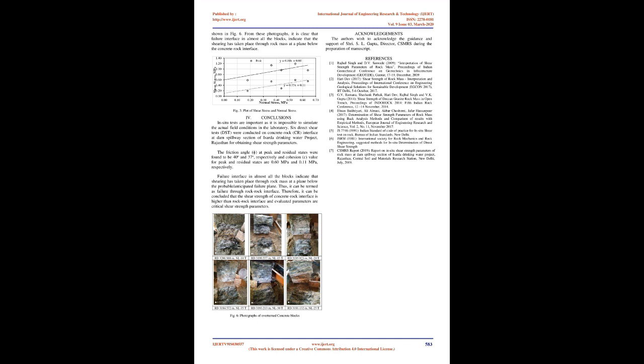The blocks were overturned after the shear tests and actual area under shear was recorded and used for computation of stresses from loads. The photos of overturned blocks for CR interface are shown in Fig 6. From these photographs, it is clear that failure interface in almost all the blocks indicate that the shearing has taken place through rock mass at a plane below the concrete rock interface.